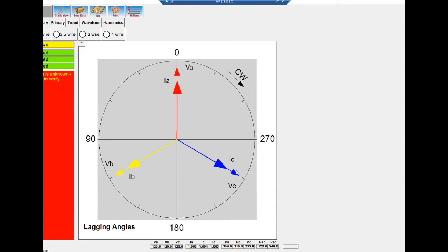So starting with the wiring check, this gives you the ability to look at the vector diagram at the site you're at. Like I was saying earlier, with the site I have, perfect 0, 120, 240 Y service I'm generating into this, I see my A, B, and C phase voltages and currents all lined up perfectly across, as you would expect in a perfect, true three-phase Y system.